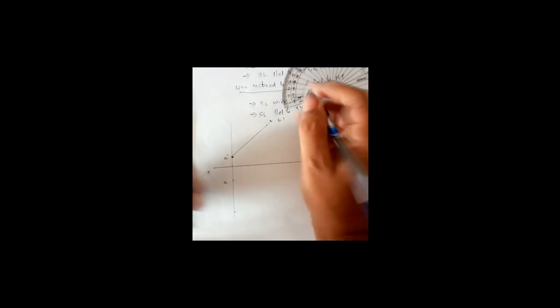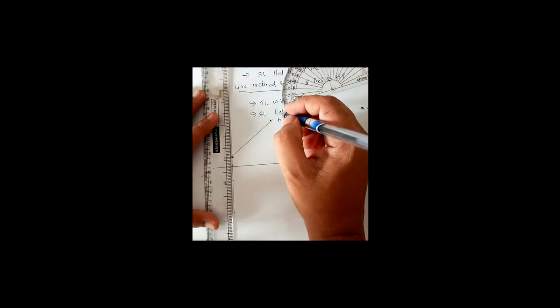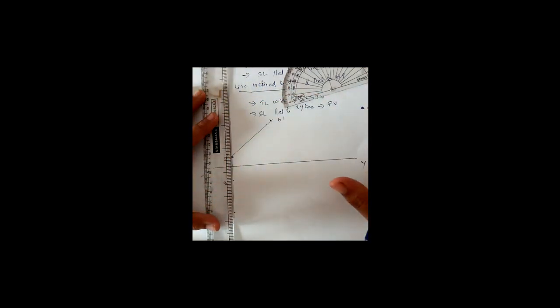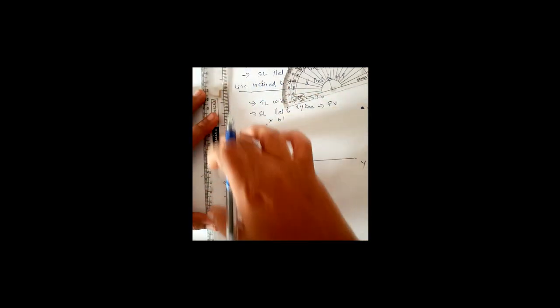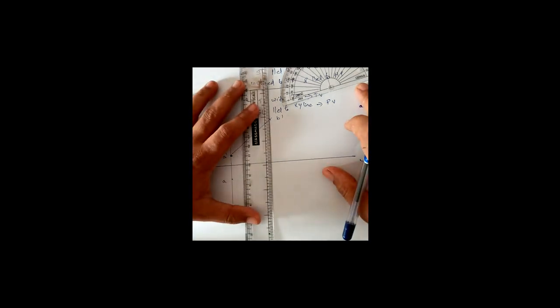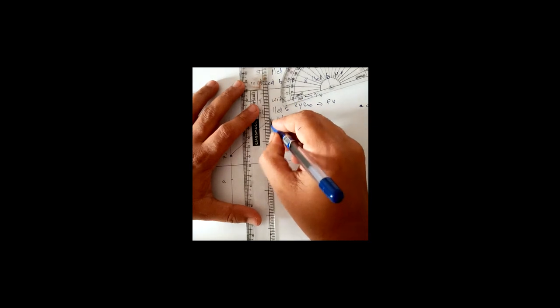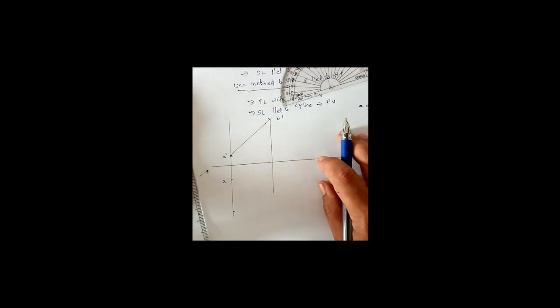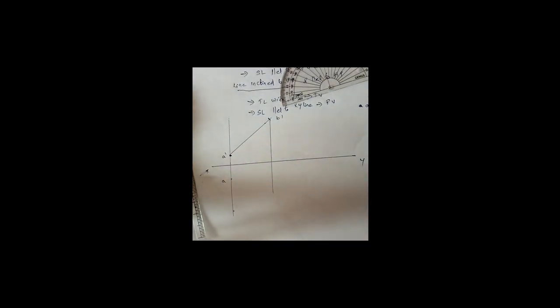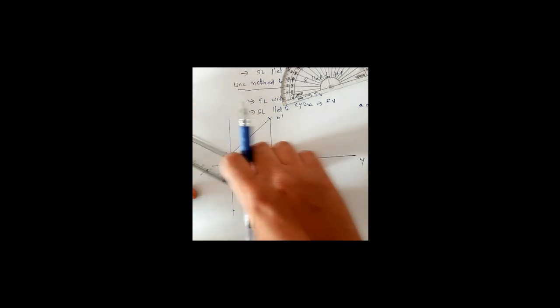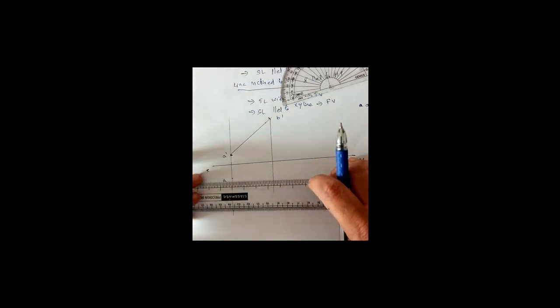Now draw a projection line. So now projection line means you can draw a line parallel to this line. So for that you can use sliding scales. So the projection line, and one view is true length with the true inclination and other view is shortened length parallel to xy line. So other view should be parallel to xy line.